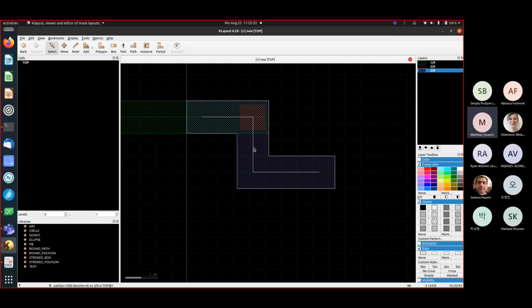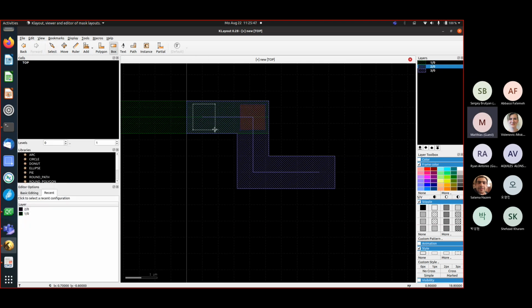I just took this opportunity to show you some more features. I wanted to actually change the path so it goes like that. Because what I want to do is create a new via here to show you this feature, like that. So that's how a double via looks like, and the likelihood of such a via to fail is pretty low.